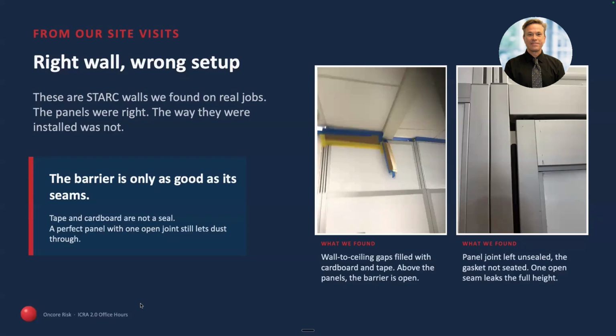And so, remember, you're going to put up these barriers, and have the barriers, as I mentioned earlier, with a zipper or a door. It has to meet the same requirements as we do with fire doors and fire smoke doors in hospital, less than 1/8 of an inch gap.